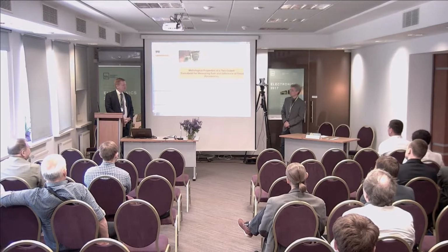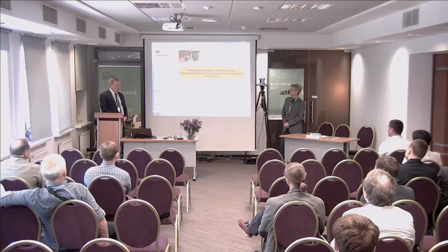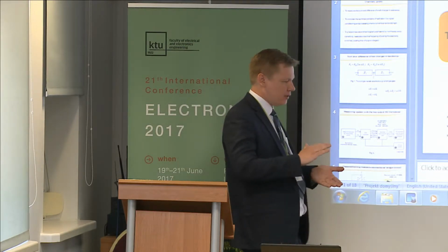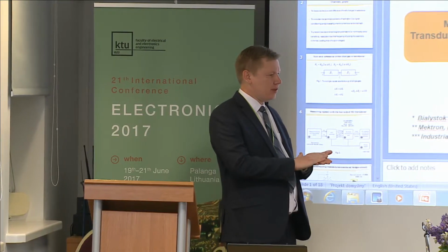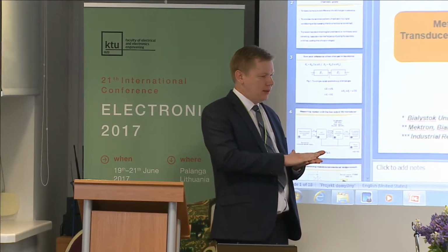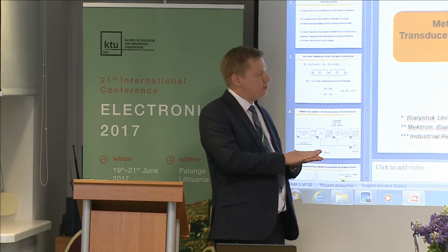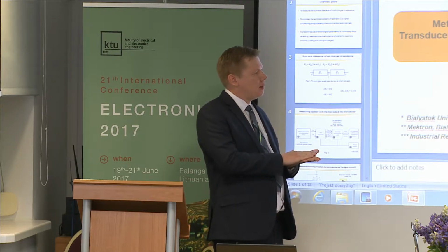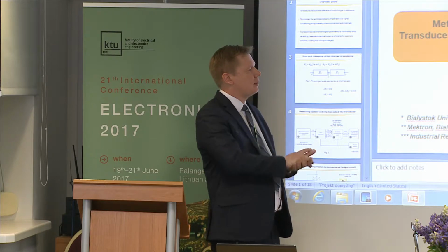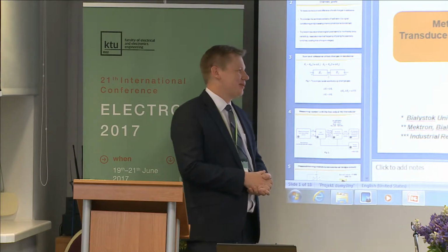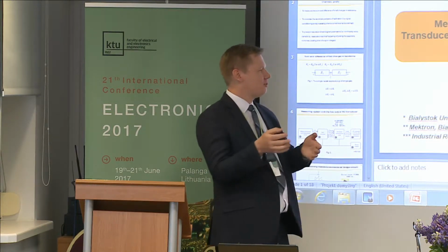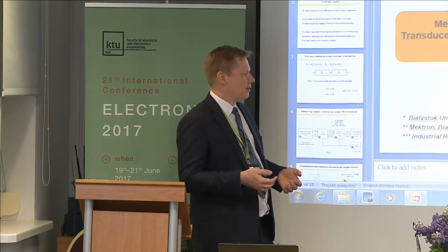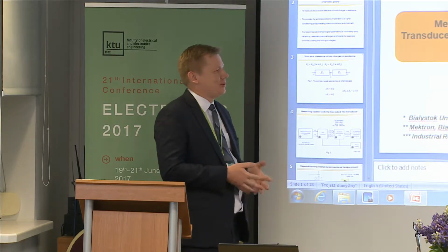Do you expect some nonlinear behavior from real sensors? Yes, I think so, because if we have, for example, strain gauges, we glue it to any surface, and there is some nonlinearity caused by this. If we stretch and compress, that's why I used the cut boxes, because I would have nonlinearity of sensor and nonlinearity of circuit, and I would not make any conclusions.